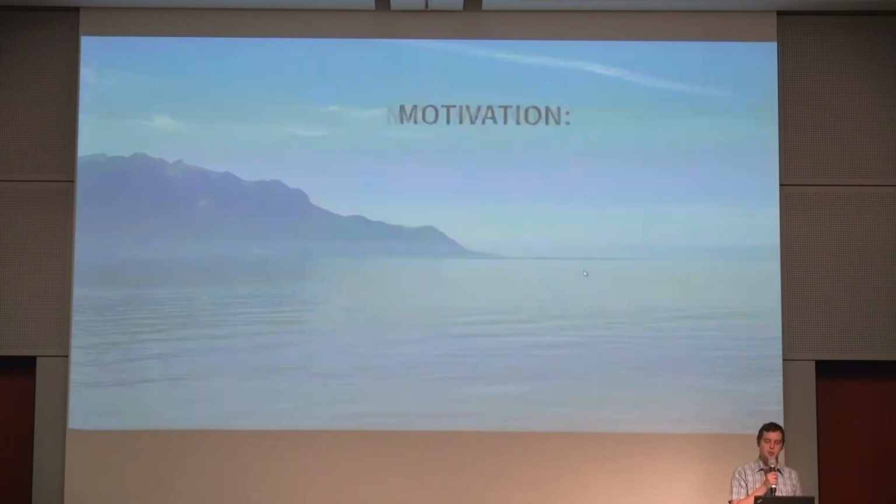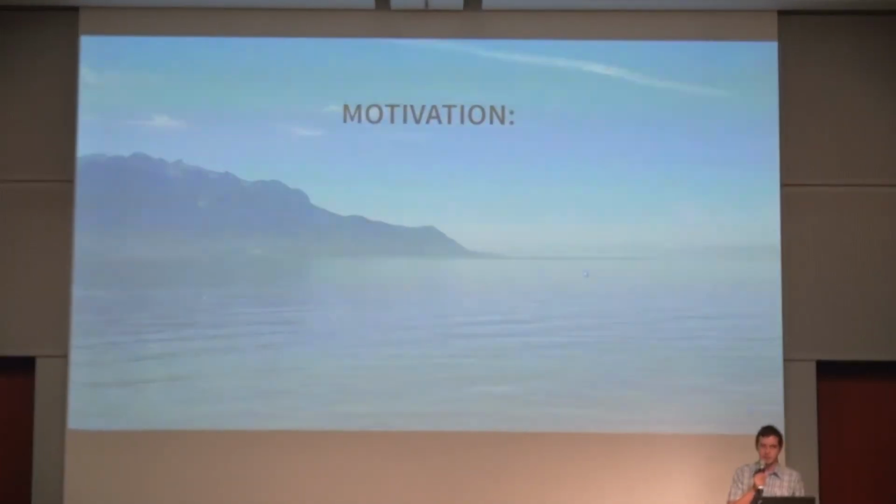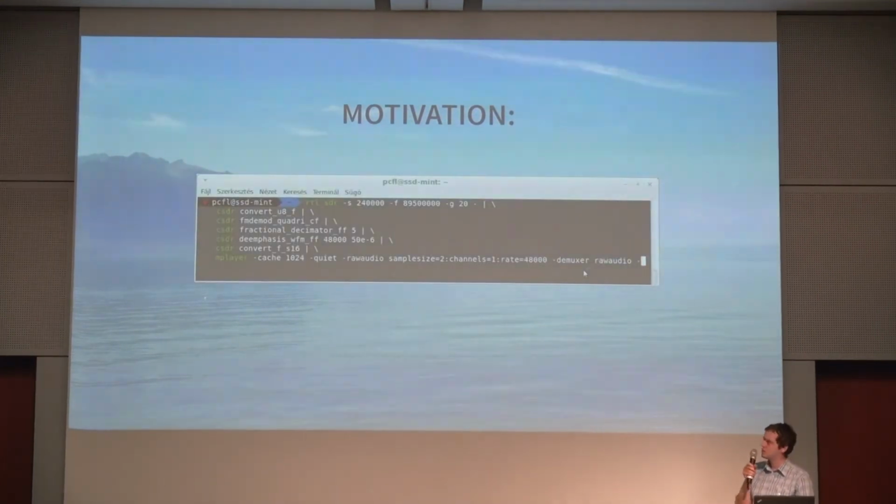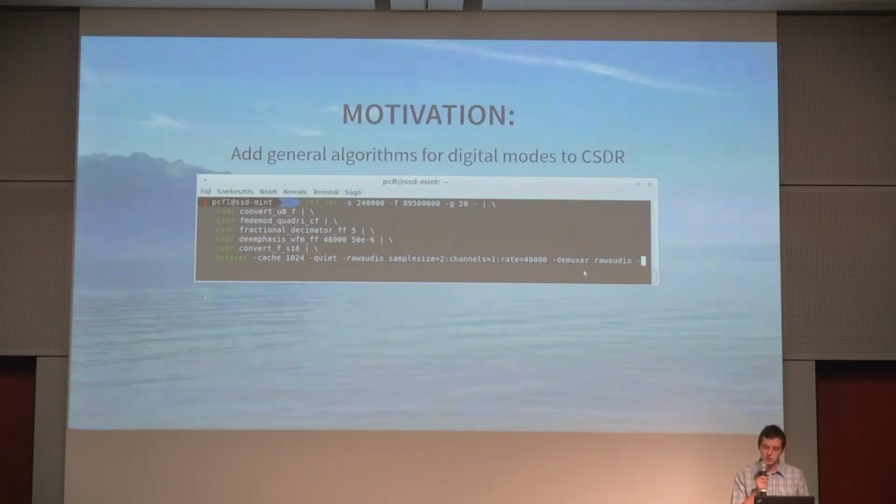The other motivation was adding digital mode support to CSDR, which is a command line tool behind OpenWebRX that I use for DSP. So it's also developed by me, and it can be used to build simple signal processing data flows from the command line, like this one, which is an FM demodulator. I want to add general purpose algorithms for decoding digital modes into this one.